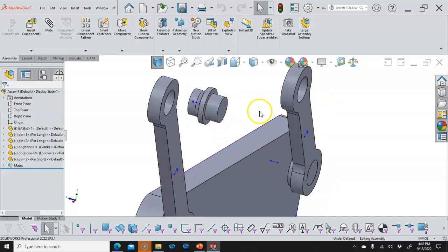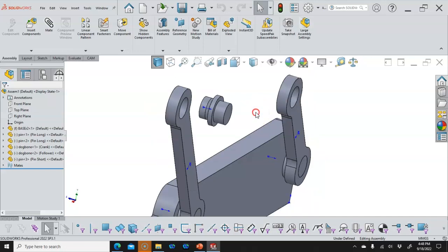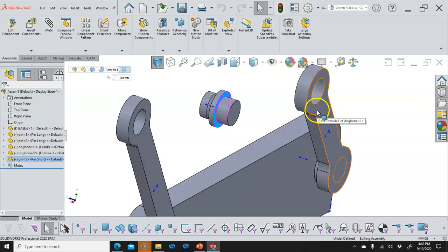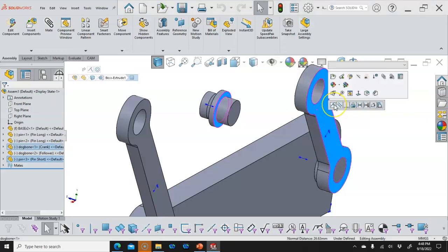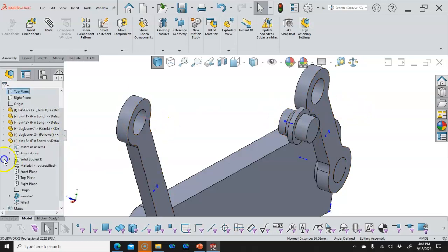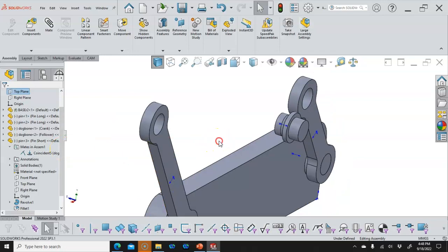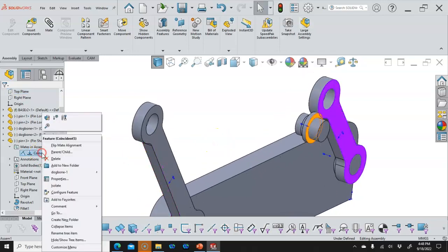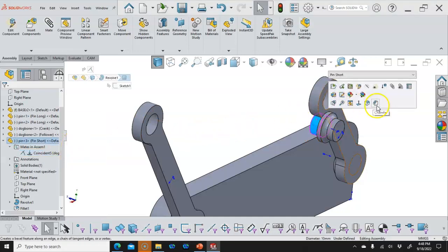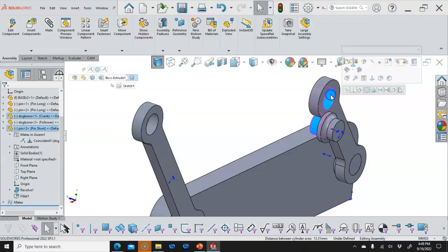So it's kind of looking like the coupler at this point, but I'll have to go through and double check my logic. All right, so if I go coincident, and then since it moved away too fast, I'm not getting the little pop-up box, so I must be moving away from it quicker, but I can flip the mate alignment, and then we'll select and control select concentric.